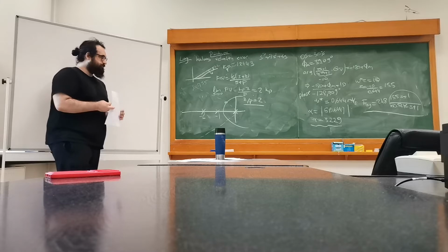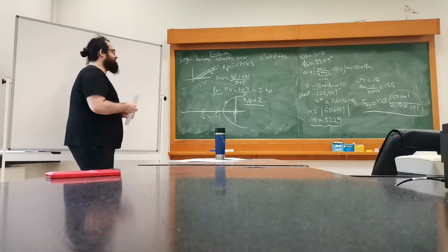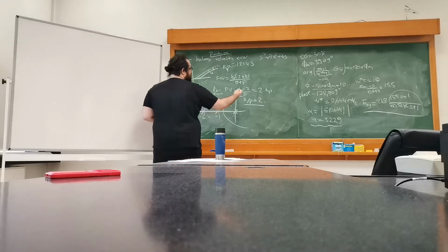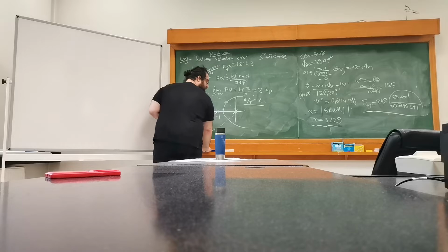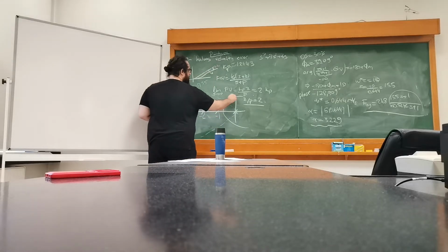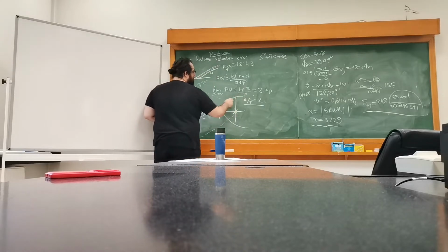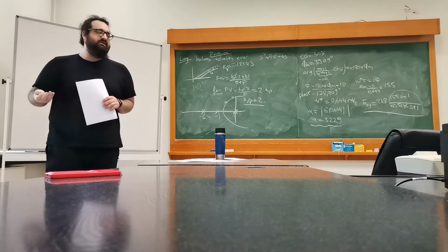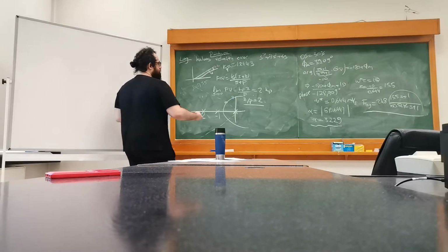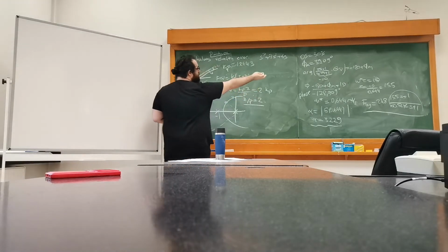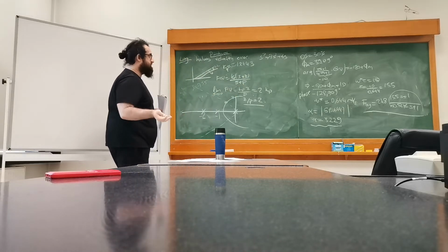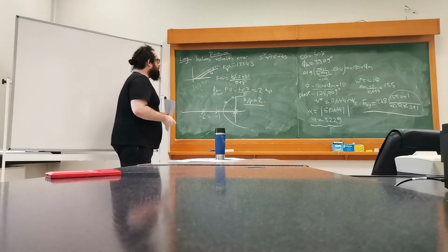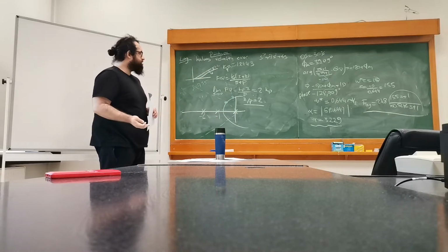Because it's on the root locus, there is a certain omega n value, etc. Now we want to increase the gain so that we have 2 times that, and let's assume that it corresponds to this position here, because k increases. Therefore, somewhere here is our actual solution. But can you see the problem here? If I increase the gain k 2 times, instead of picking 1.24, I'm just picking 2.48. Then I will have a lower zeta value. This will be higher overshoot, and I don't want that.